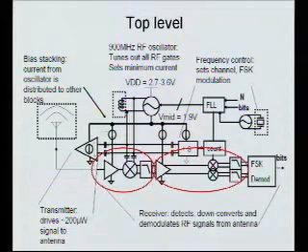So how does it know when a signal is coming? It knows because signals are only sent once a second. So it counts until a second, and it wakes up and listens. And if there's a signal there, the guy talking to it also waited a second, and while they're talking, they can resynchronize, and then they can shut down, wait a second, and wake up again.